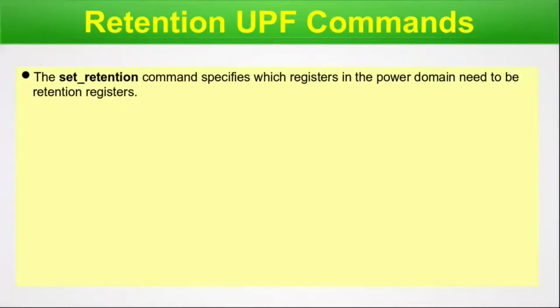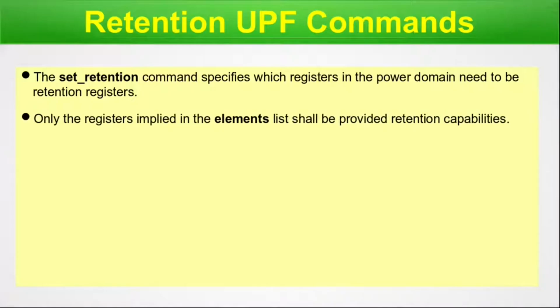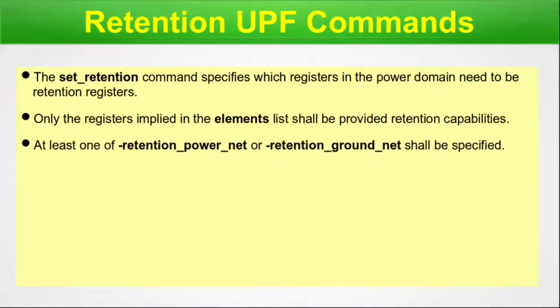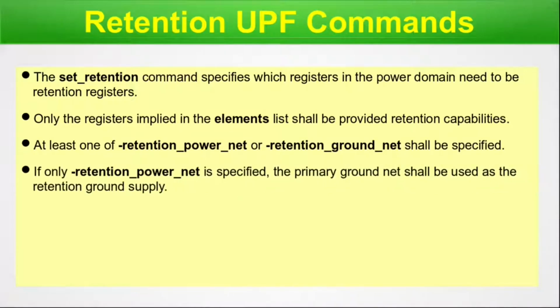The retention UPF commands. The set retention command specifies which registers in the power domain need to be retention registers. Only the registers implied in the elements list shall be provided retention capabilities. At least one of the retention power net or retention ground net shall be specified.